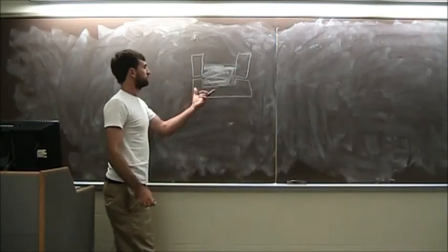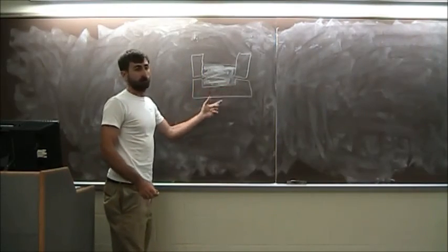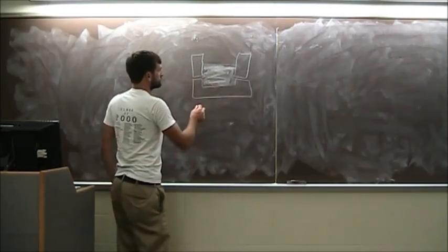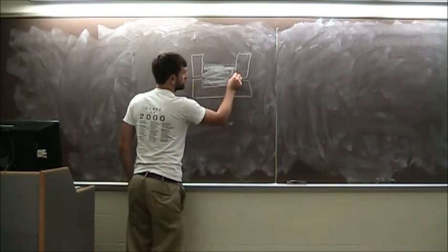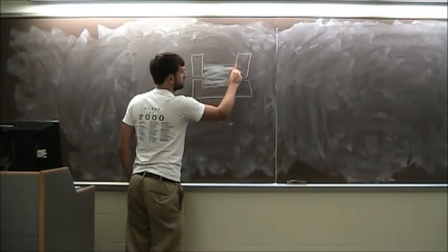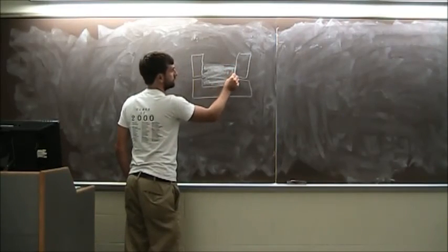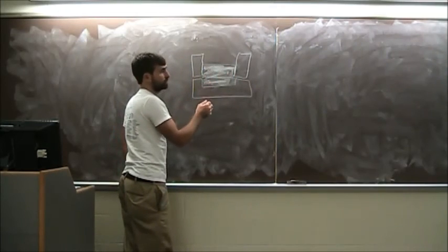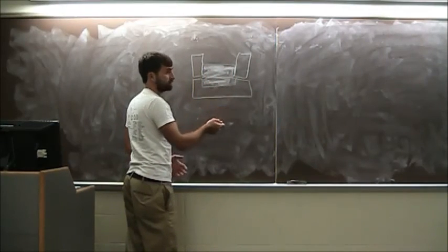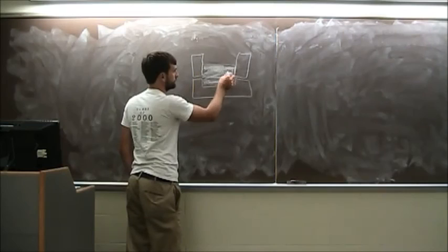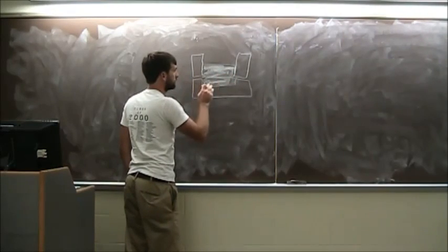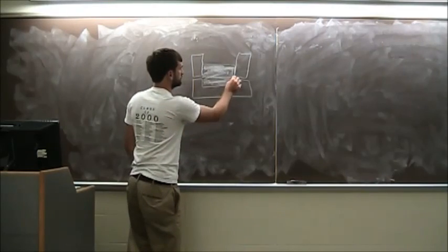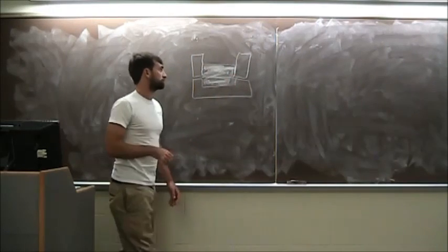These things are only a couple of inches in diameter and maybe an inch or two high. So when you shear this thing, you have stress concentrations at these boundaries that are not seen here. So you have non-uniform stress distributions throughout the sample. So really what you're seeing is kind of an average shear stress, and not really what the peak is in the sample, because it's a non-uniform stress distribution.